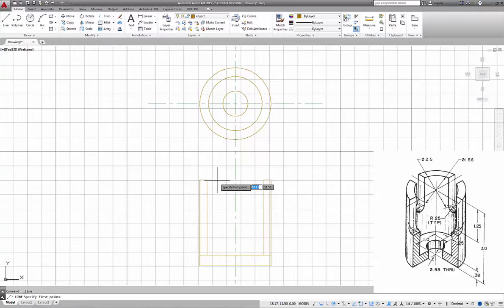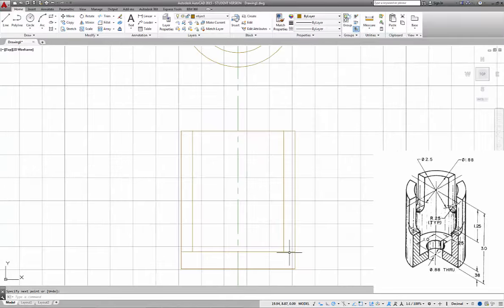And since this object is circular, we will have a line across the top in the middle. Alright, so now I've got to clean up the corners. So we'll move the corners in. That's easy to be done via the grip environment. And so our notch is 1.25 inches below the top, so 1.25. So I just did an offset command. I'm going to offset this line down 1.25.